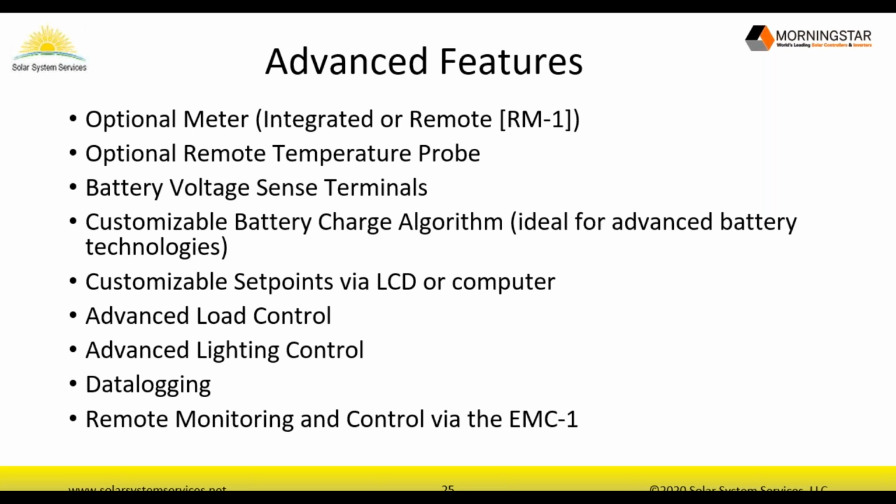Normally, if the ProStar is in close proximity to the battery, you do not need that. However, if it is in a separate box, I highly recommend that you use a remote temperature probe. I've seen several problems from people that put the charge controller in one box and the battery in another, and they actually damaged a very nice set of new batteries because of that. And once they hooked the temperature probe up to it and put a new set of batteries in, they eliminated the problem. There's also battery voltage sense terminals.